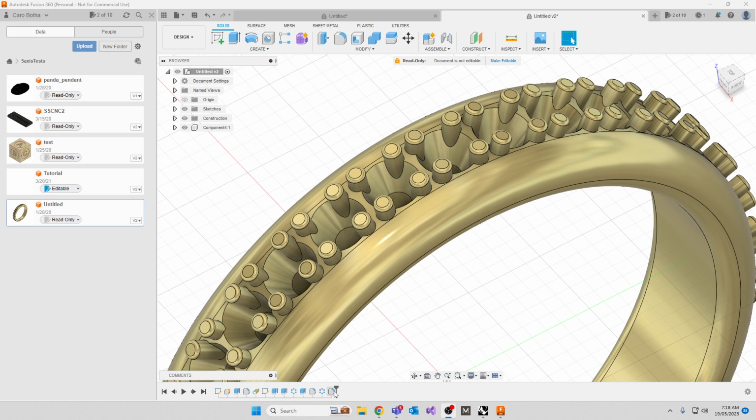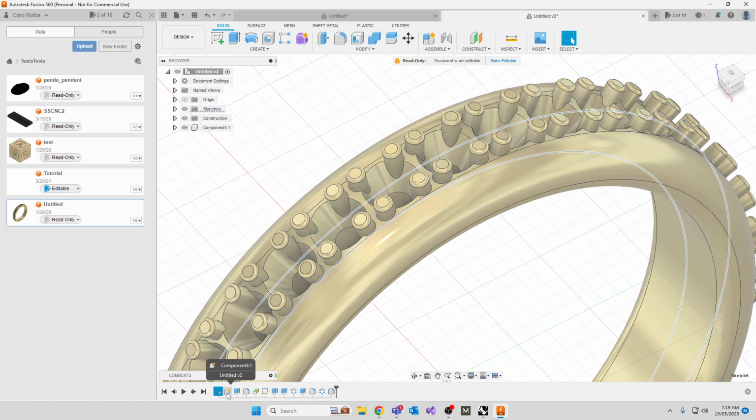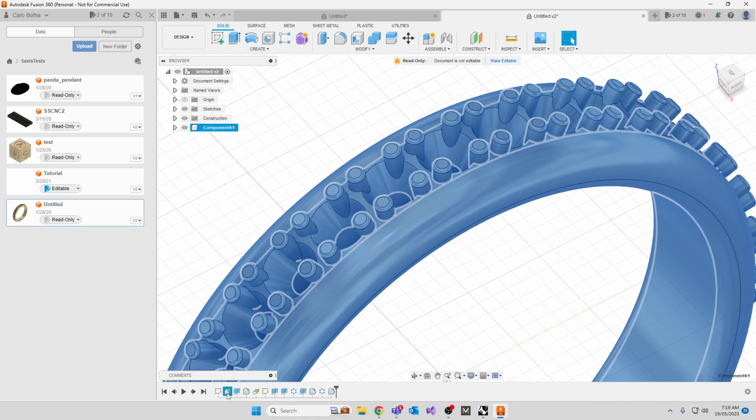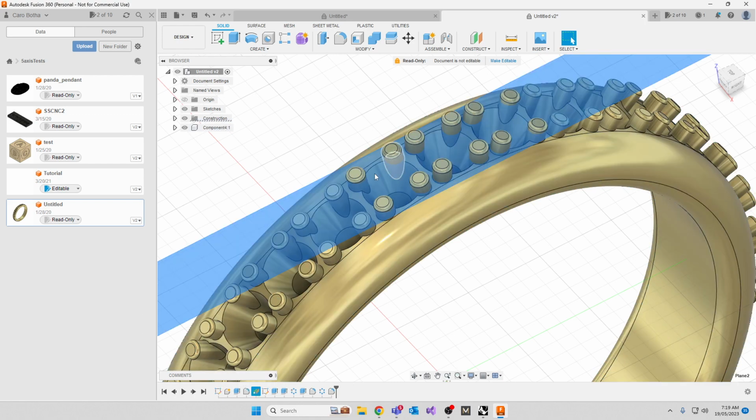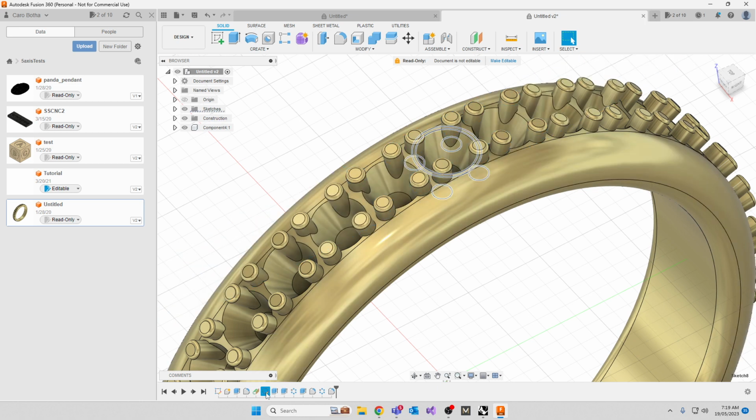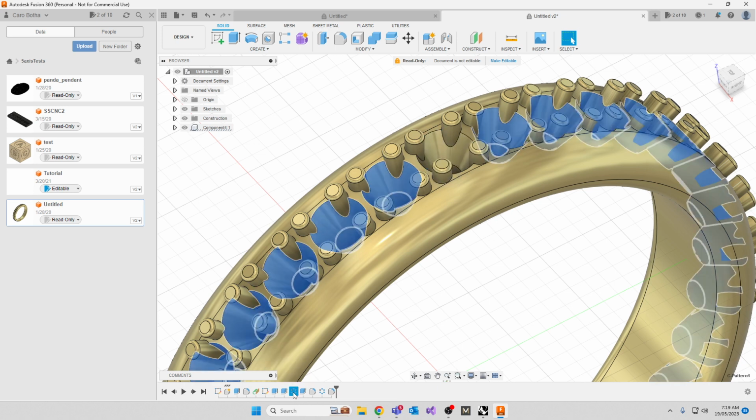So I'm working with Hui, and I've explained to her, if you look along the draw history of this job, it's different to Rhino's history. I started with a sketch. On that sketch, I drew out a curve, and then I turned it into a component. I extruded. I did a fillet. I drew another sketch up the top here. On that sketch, I drew some circles. Some of the circles I extruded outwards. Some of the circles I extruded inwards. And then I did a polar array of the whole lot.